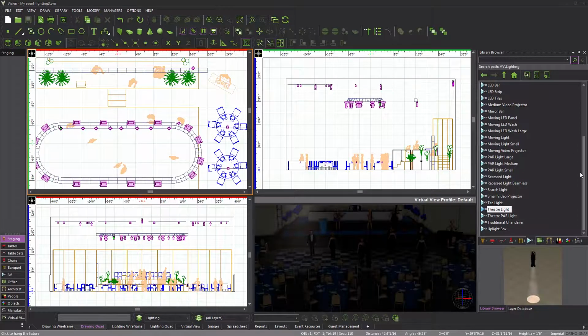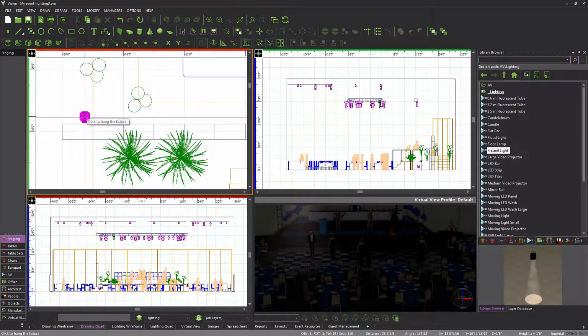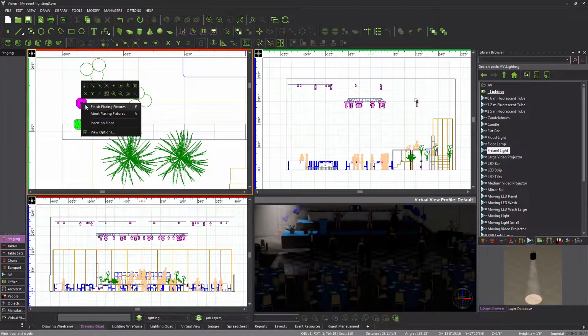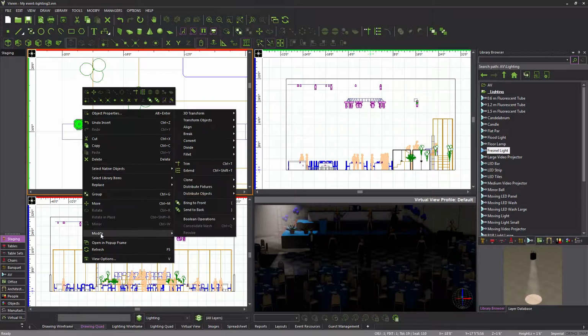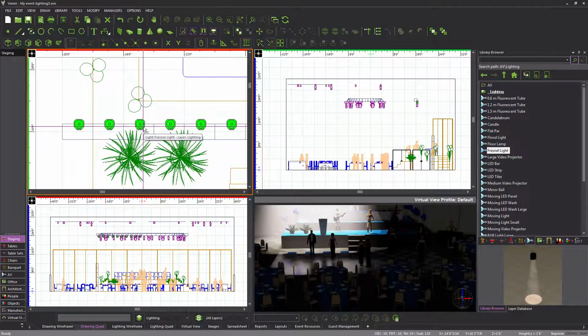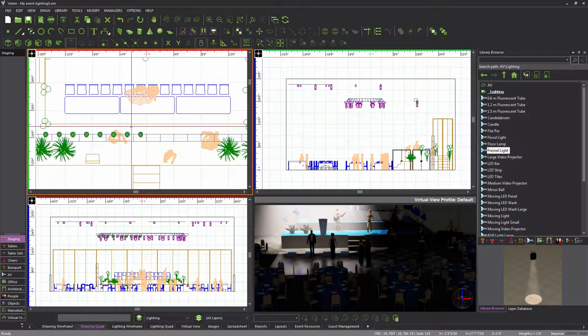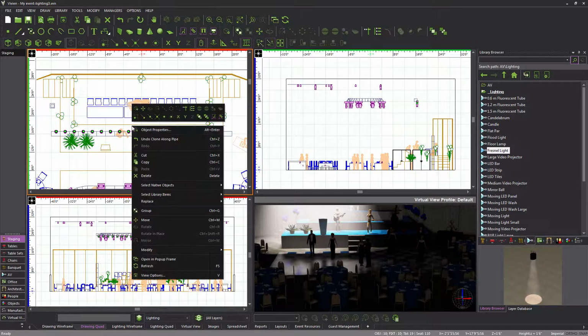To light the stage, we will hang a single Fresnel fixture from the upper side of the truss above the left side of the stage and clone it 10 times at an interval of 2 feet. This interval is a little too small, so let's increase it to 3 foot 6 when we center distribute these fixtures.